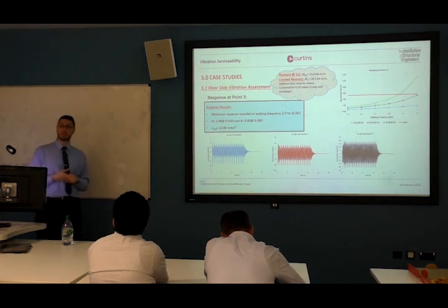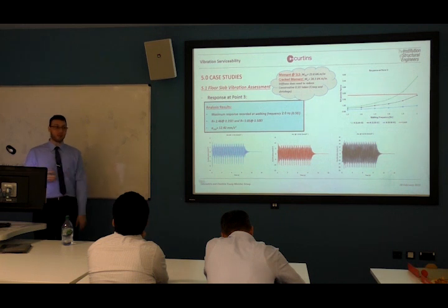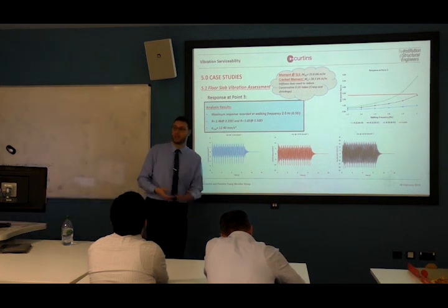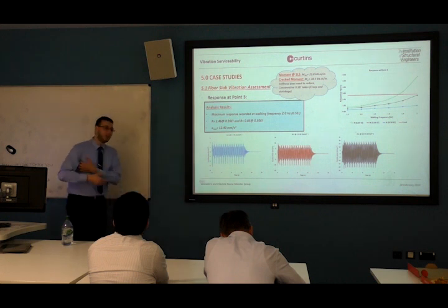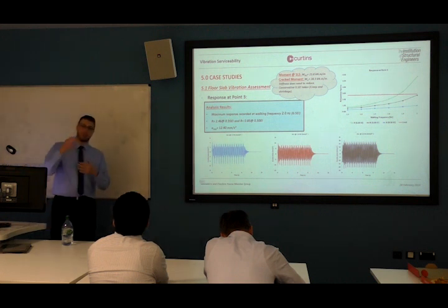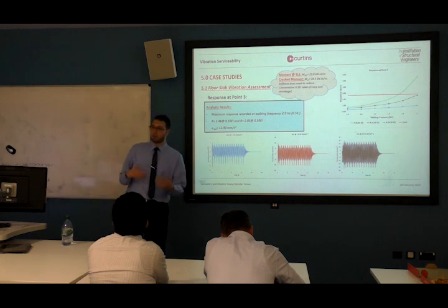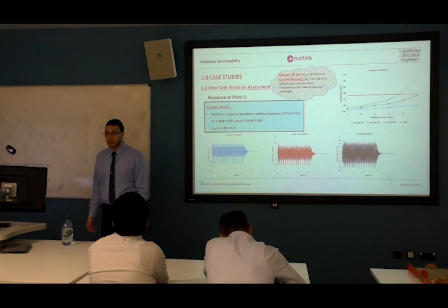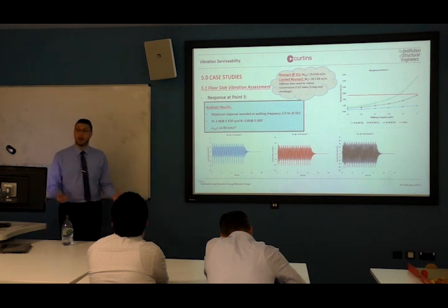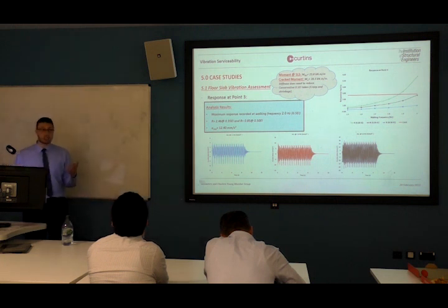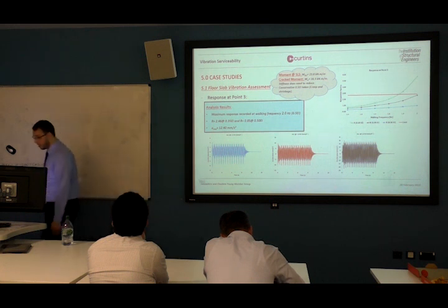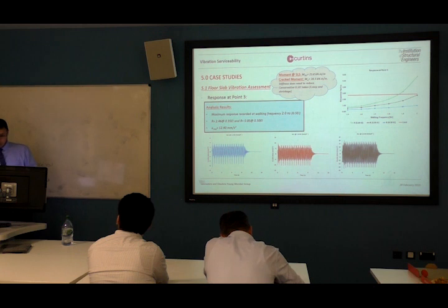And in this area, you're not bothered if someone is walking around you. It's a very congested area. Someone is eating pizza. Someone is drinking something. So you're not really bothered if someone's walking beside you. So you say, okay, 8 is fine. Maybe 10 as response factor is fine. So it's actually based on your engineering judgment to check whether it is okay or not.